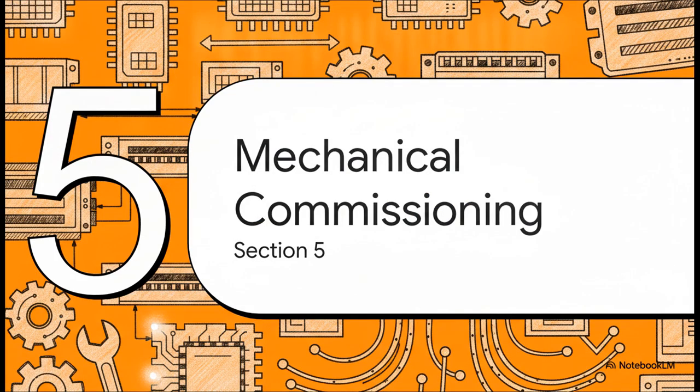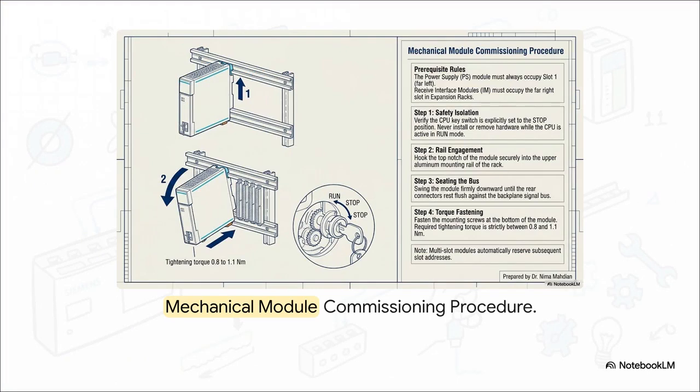All right, let's bring all this theory back into the real physical world with Section 5, Mechanical Commissioning Procedure. Commissioning a module isn't just plugging something in. It requires precise physical mechanics. Before a single piece of hardware is manipulated by your hands, the CPU key switch must be explicitly set and completely isolated in the stop position. You never, ever install or remove hardware while the CPU is actively running in run mode. Safety and hardware integrity are the absolute non-negotiable prerequisites here.